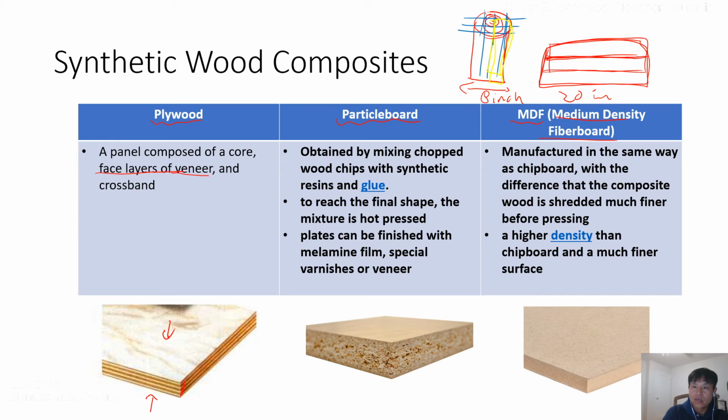That is veneer. We attach the outer layer to the top and bottom, and the inside we make like a sandwich, adding certain layers of thin wood panel, and then make this pattern. So you can see the color differences. In general, plywood has 3 layers, 5 layers, or 7 layers, depending on thickness.